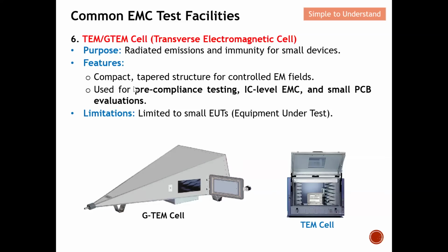They are mainly used for pre-compliance testing, for IC level EMC and small PCB evaluation. The key limitation is that they are really limited to very small EUT. I believe this kind of EMC test facility has more or less been phased out, so they can be used to test just a very small EUT or DUT.